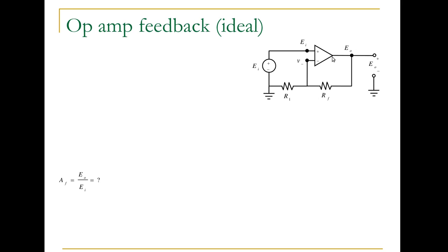Our open loop gain was one thing, but now we have a closed loop system, so we'll have a new gain. And doing this can also improve the bandwidth of the op amp, bandwidth meaning the frequency beyond which the gain starts to decrease. When we add feedback, then we get a higher frequency.